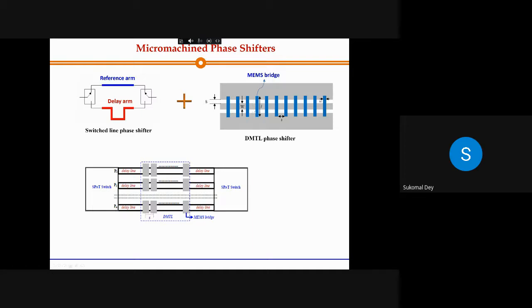Now, when you are adding this capacitor, you are increasing the capacitance on the line, on the center line, on the RF line, on the signal line. Whenever you are increasing the capacitance, the overall line capacitance has increased, so the impedance is reduced from 75 ohm to, for example, 60 ohm.